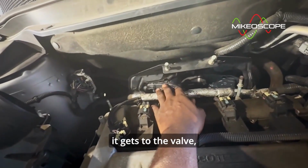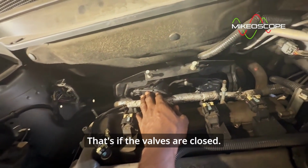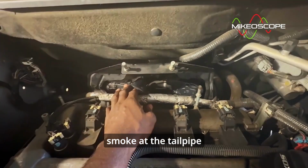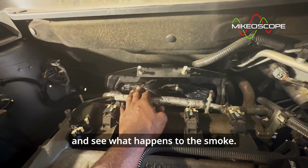So I expect that when it gets to the valve, the smoke stops right there and I start to build pressure on the smoke machine. That's if the valves are closed. I do not expect to see smoke at the tailpipe, okay, because the valve should be closed. So we're going to turn that on and then we're going to observe and see what happens to the smoke.